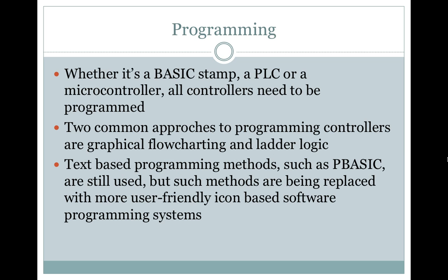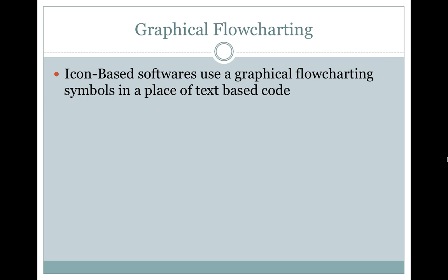Programming. Whether it's a BASIC Stamp, a PLC, or a microcontroller, all controllers need to be programmed. Two common approaches to programming controllers are graphical flowcharting and ladder logic. Text-based programming methods such as P-Basic are still used, but such methods are being replaced with more user-friendly icon-based software programming systems. Graphical flowcharting. Icon-based software uses graphical flowcharting symbols in place of text-based code.